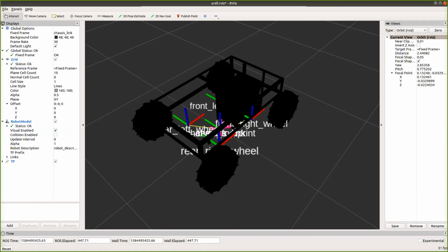Chat. GPS, the Fidget GPS. The one you posted? I believe that SkyTrack Venus chipset is a single frequency. It might be multi-constellation, but it's probably not going to handle any RTK corrections for you. I doubt you can get any raw data out of it either, like Kyler was mentioning. I looked and I didn't find anything about raw data from it.